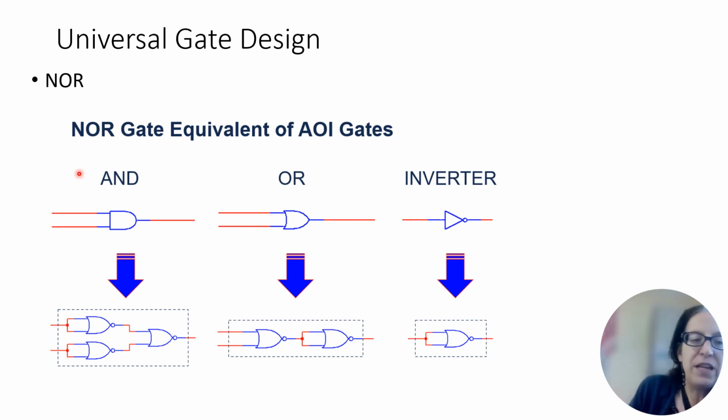And then these are actually the same as well, as long as you switch them so that they match. So with a NOR, OR is the one that's fairly simple. An OR gate, you want to OR them, but you don't want the negation. So you would put them in the NOR gate and then run them through the inverter to undo the inversion that you don't want.